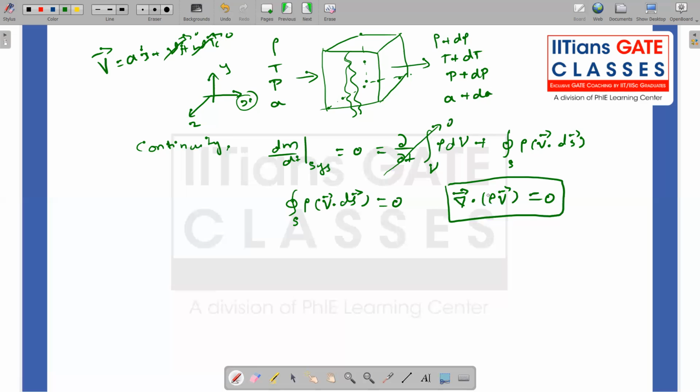Right? So I'm not showing all the steps because we already did this in our previous classes. Now, because it's a one-dimensional system, I have velocity which has only one component, that is in the x direction. So if I do that, what do I get? If I expand this term using a vector operator, that becomes rho times divergence of velocity plus velocity vector times gradient of density.